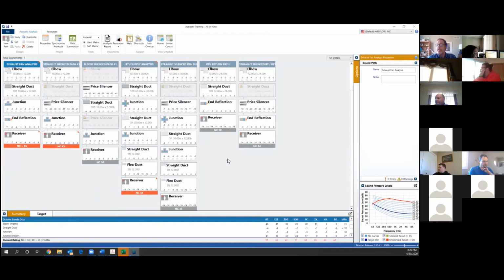Yeah. And if there aren't any questions, we really appreciate you coming in. I'm doing one more class, at least for now, on just how I look at fan selection software. We can all pick a fan, but how we pick a fan is kind of the subject at hand. So I hope you guys at least look: silencers are cheap, flex is cheap. Keep yourselves out of trouble. Know when you're going to be needing one. Fixing acoustic problems after the fact is really, really tough.